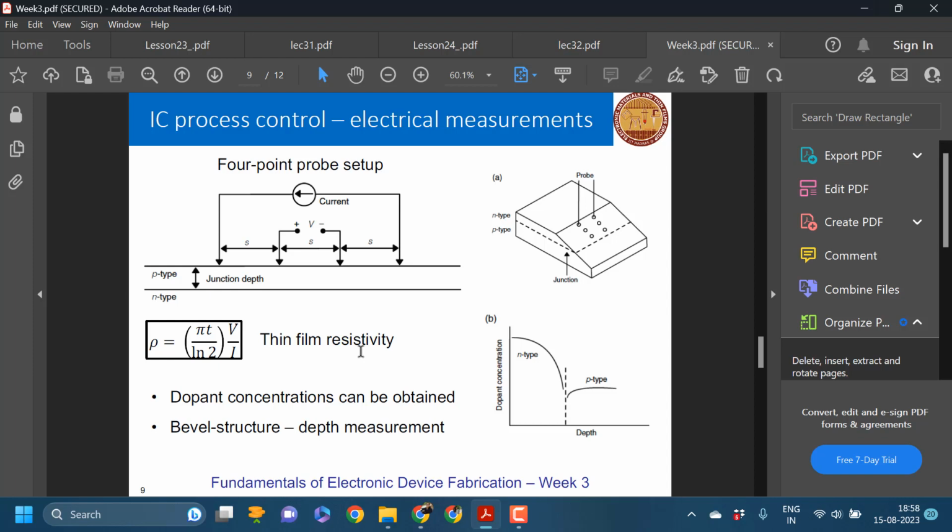Yeah. So basically, integrated circuit manufacturing is like an assembly line process, and there will be hundreds of steps involved before we get the final article, right? So process or device evaluation is critical because we need to ensure that all the chips or dies or every component is working correctly after each step without significantly altering the total process cost and time. This is because if we wait to evaluate the component after the final stage, and it is found to be not working, then a lot of time and money involved in the process will be lost.